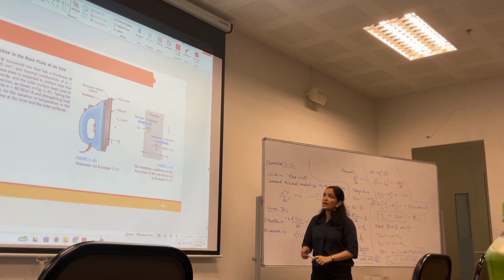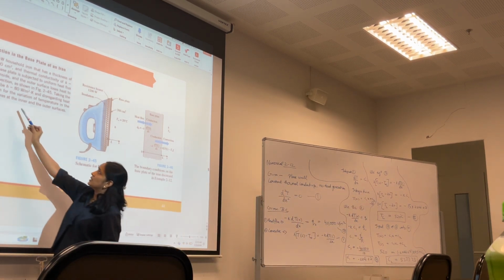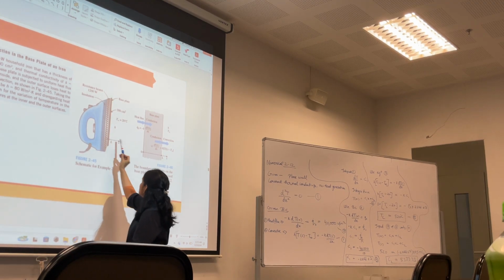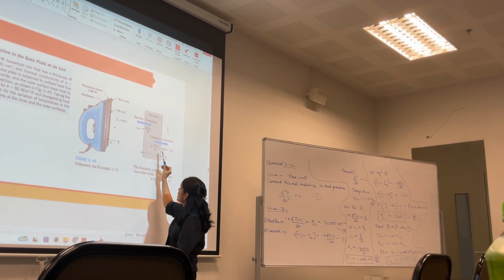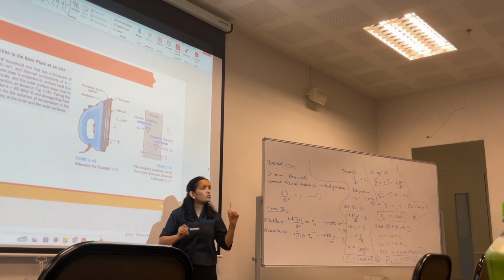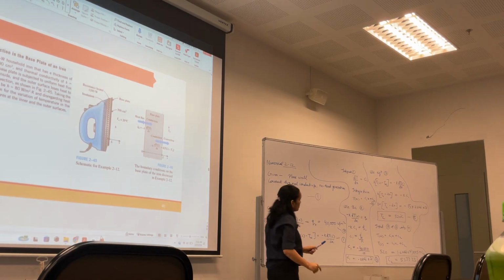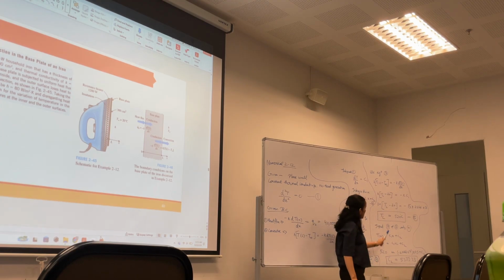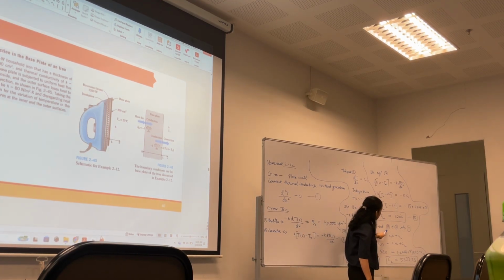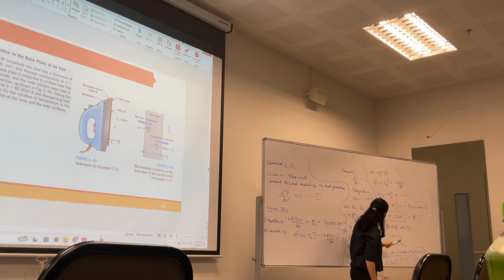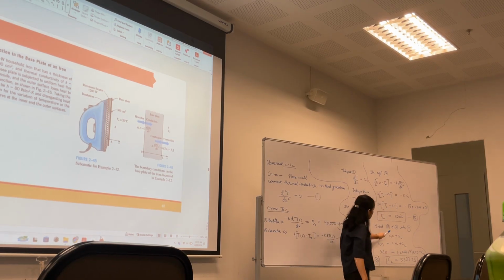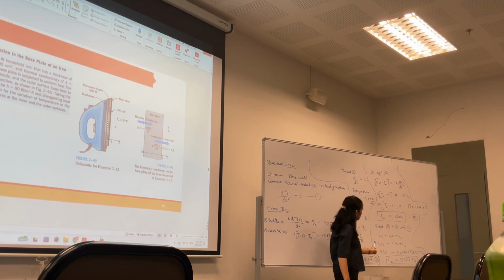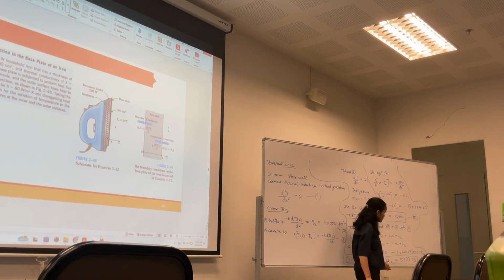They are also asking temperature at the inner and outer surface. Inner surface is this T0, outer surface is Tn. So you have to also find T0 and Tn. So we have found Tn here. Okay. Now you have value of Tn, 5, 6. 5 is this, 6 is this. You input in 4. 4 is this. You input everything in here, you will get the value of C2.